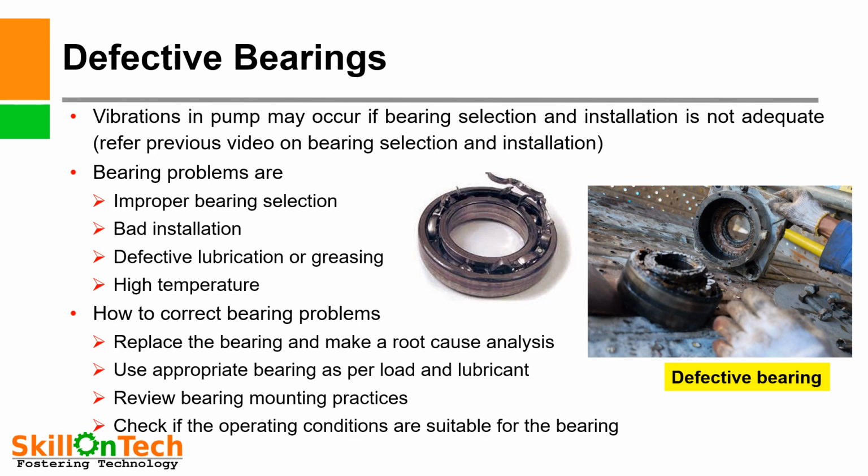How to correct bearing problems? Replace the bearing and make a root cause analysis. Use an appropriate bearing as per load and lubricant. Review bearing mounting practices. Check if the operating conditions are suitable for the bearing.